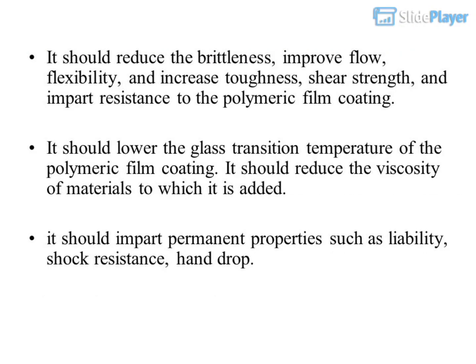It should reduce the brittleness, improve flow, flexibility, and increase toughness, shear strength, and impart resistance to the polymeric film coating. It should lower the glass transition temperature of the polymeric film coating. It should reduce the viscosity of materials to which it is added. It should impart permanent properties such as flexibility, shock resistance, hand drop.